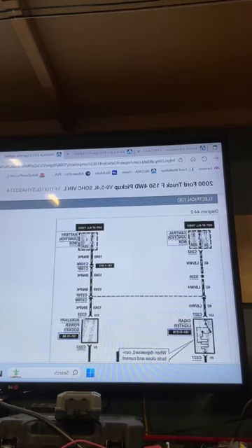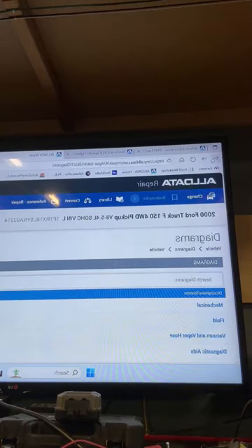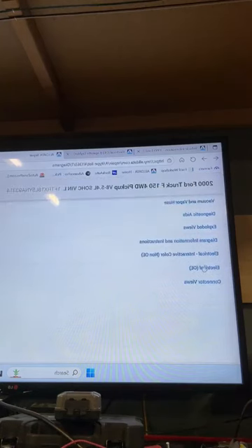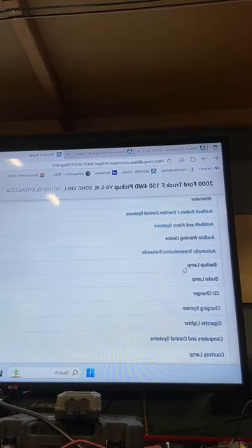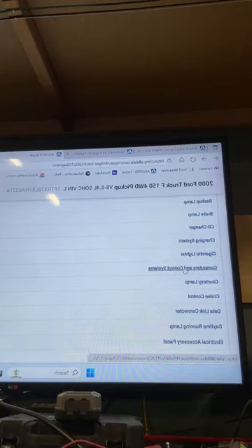So we're looking at something in the dash that's going to be a switched power. So let's go back and think of something in that area that only operates on switched power. Changer, I mean, that's a possibility. Something in the radio, perhaps.